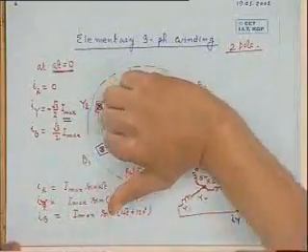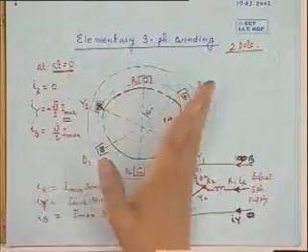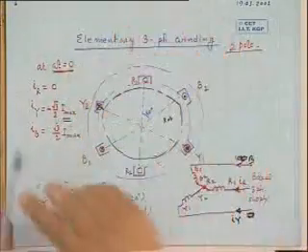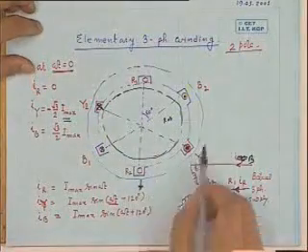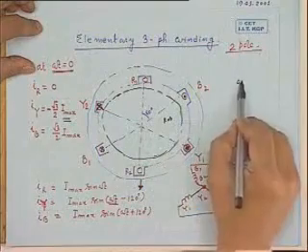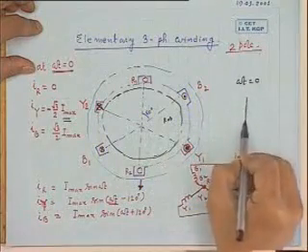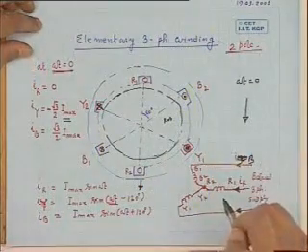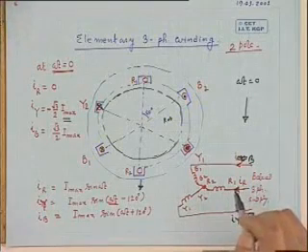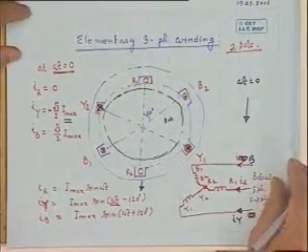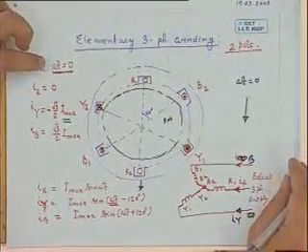See, these are two coils, on this side cross, this side dot. So the situation is like this. Current is going in, coming out. So it will be directed downwards in the vertical direction. So the resultant field at omega t equal to 0 will be somewhat like this, downwards. Are you getting?